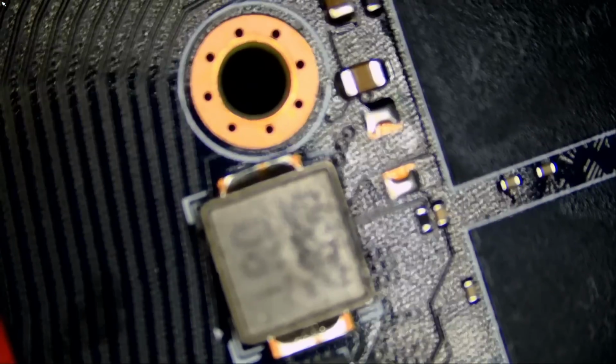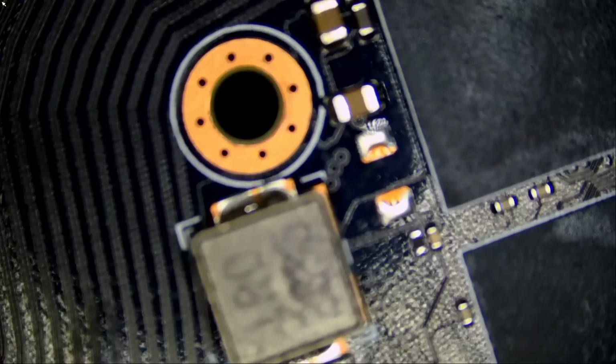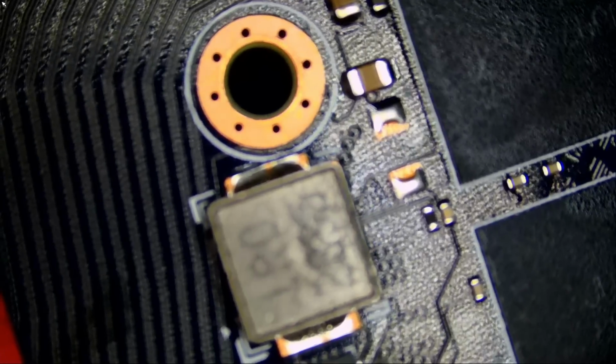What does that mean? 1, and the 3 beeps were actually not too fast. Toot, toot, toot. I do not know what that means. It's posting, but black screen. Let me turn the power supply off, and I'm going to turn it back on and quickly measure some voltages. Power supply on. Meter in voltage mode. Oh, now the 3 beeps are faster.